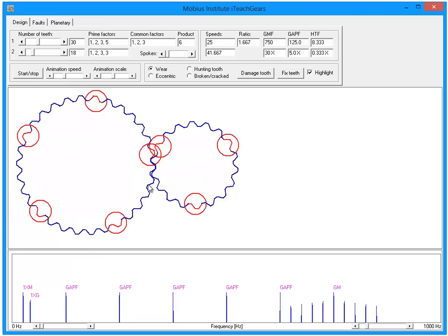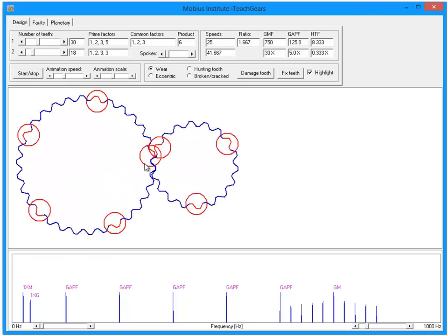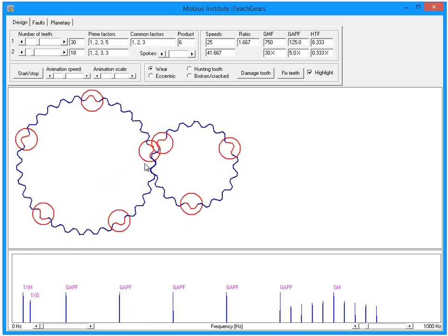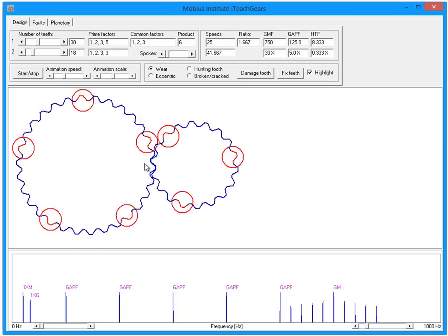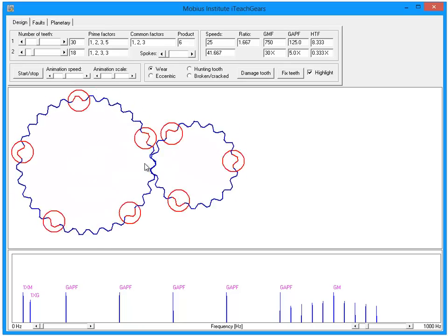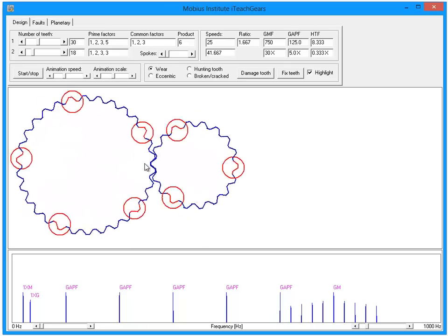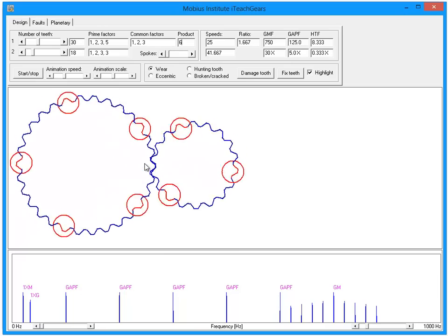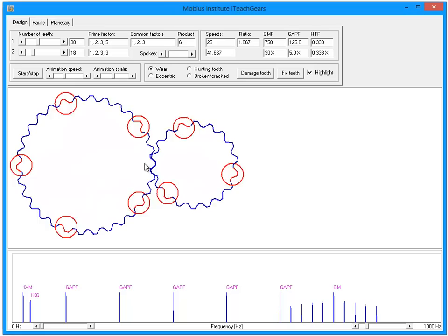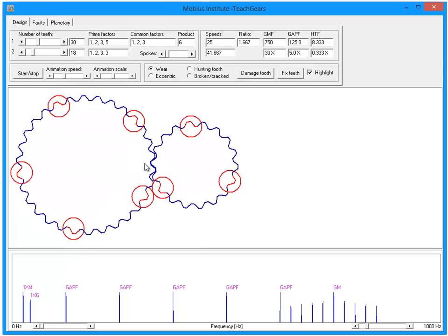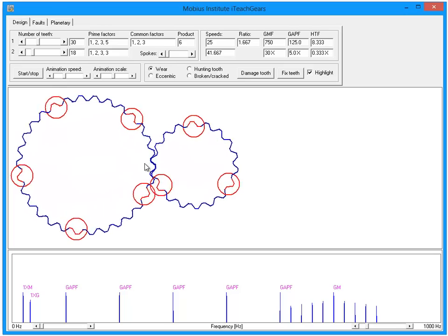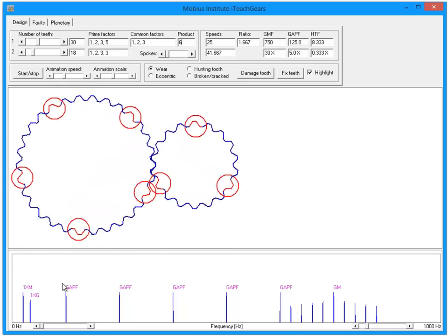And if we have any fault conditions which can excite that natural frequency, any impacting sort of faults with damaged teeth, then that natural frequency will be excited with a higher level of force, if you like, and therefore that peak can rise. We can also see modulation in that vibration. Instead of it being a solid impact, if the force of that impact rises and falls, then our gear natural frequency may also have sidebands. Anyway, this just explains why sometimes you might look at gearbox vibration and see peaks that you can't quite explain. They could be related to natural frequencies. They could be related to this gear assembly phase frequency.